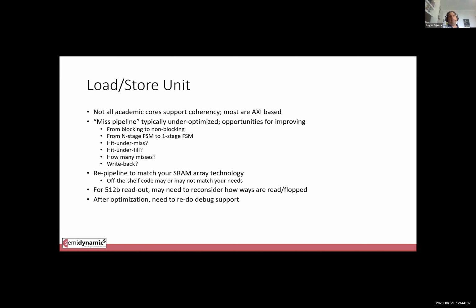And obviously indirectly, and that's definitely not the fault of the authors, after you heavily change the load store unit, you need to make sure that watch points continue to work and that in debug mode, things continue to actually operate. So there's some work there to be done. And obviously change the PMA to match your SoC memory map. That's inevitable. You have your own SoC, you have your own memory map, you're going to be doing things differently, so you'll have to change the PMA there.